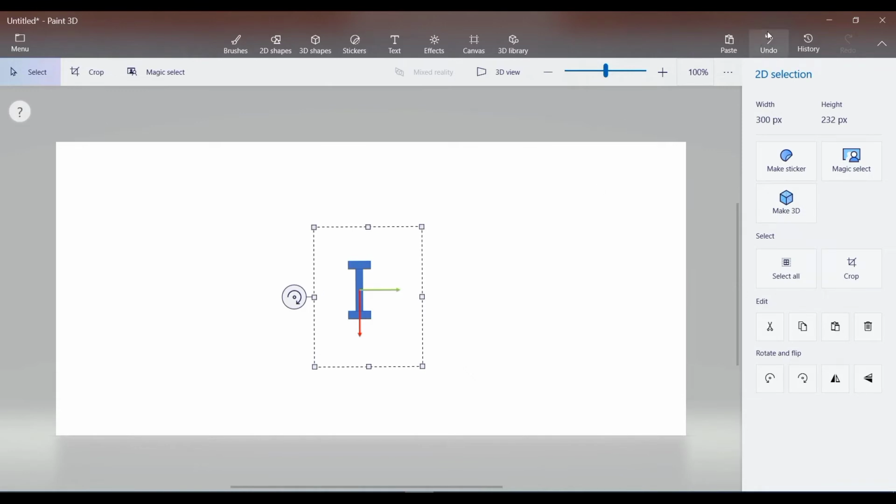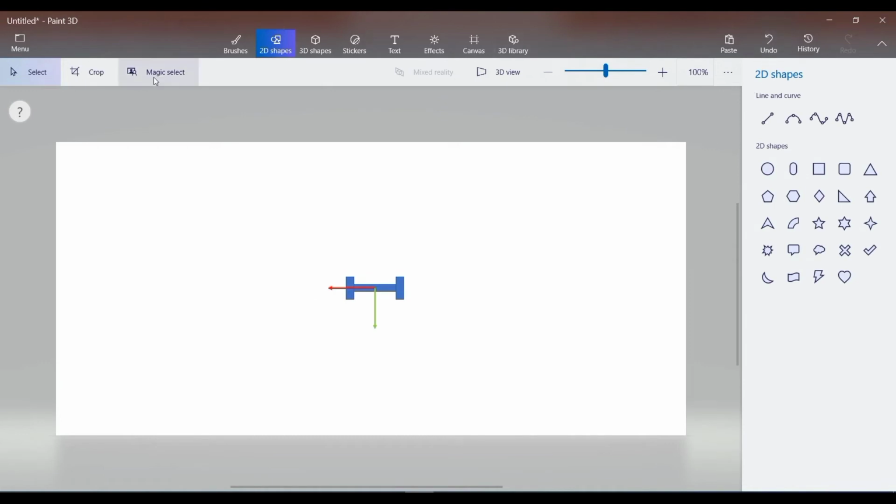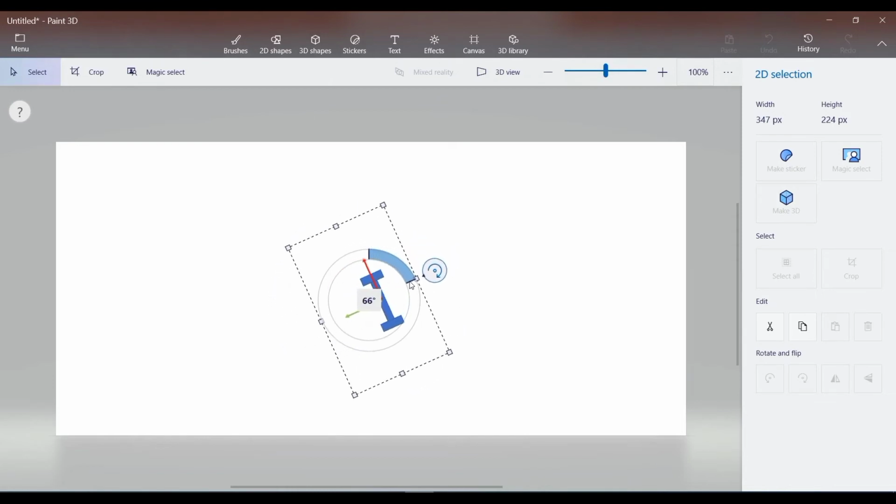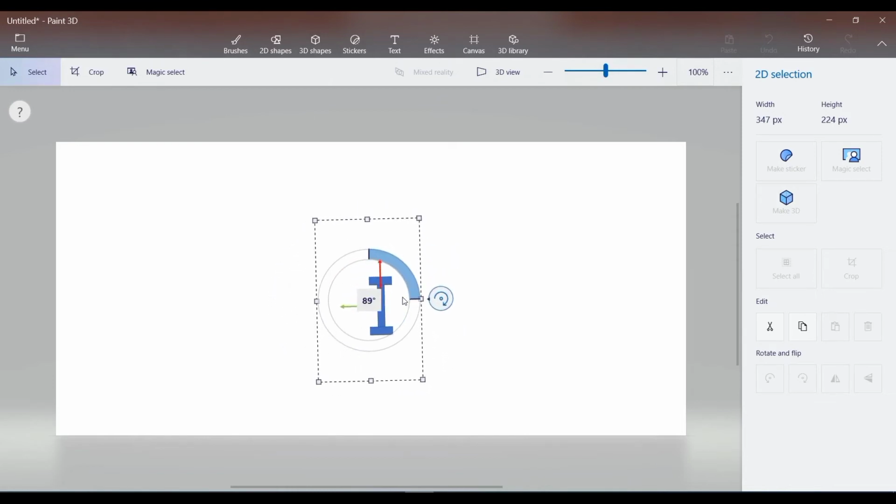On the other hand, we would also achieve a satisfactory configuration if we rotate the section in the clockwise direction instead of in the anticlockwise direction by 90 degrees. That is, clockwise rotation of 90 degrees, like this. Now, from the structural analysis standpoint, both of these configurations are acceptable. The only difference that we get is in the positive directions of the local y and the local z axis.